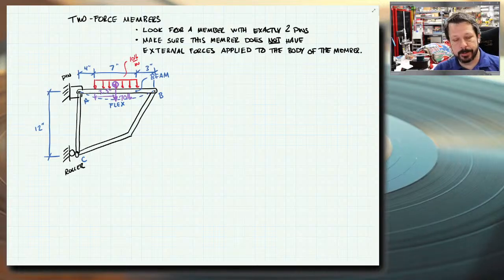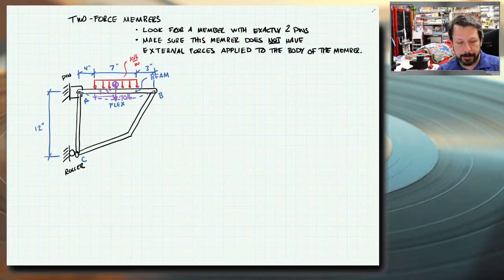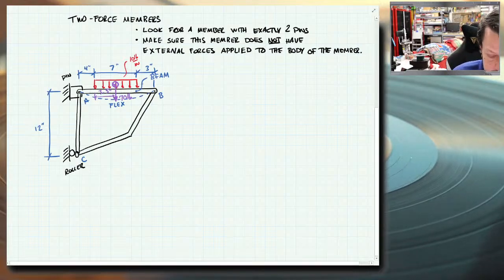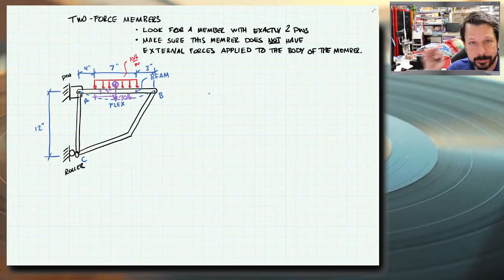So we just took the 10 pounds per inch spread over 7 inches, collapsed it down to a lumped or concentrated load of 70 pounds. 7 inches times 10 pounds per inch is 70 pounds. And then I put it at the centroid. This is a rectangular, this would be called an evenly distributed load, where basically the load is horizontal. The line across it is horizontal. That's evenly distributed. You could have unevenly distributed that have some random shape, or a triangle or a curve or whatever.